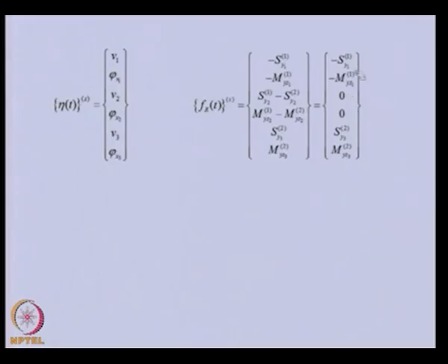Now once we have obtained the assembled equation, depending upon various kinds of boundary conditions, we can solve this problem. So in today's lecture, we started with the development of the elemental equation. We used the Galerkin method for the development of the elemental equation. In the previous class, we developed the Euler-Bernoulli beam equation of motion, and for that particular case, we started with an approximate solution, and we obtained the weak form of that equation.